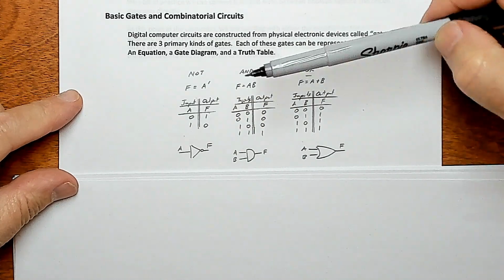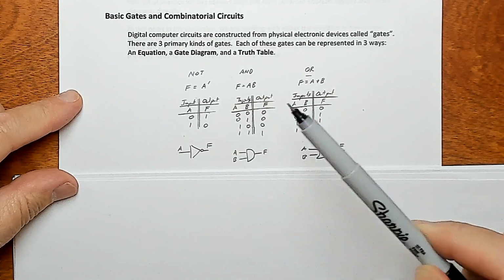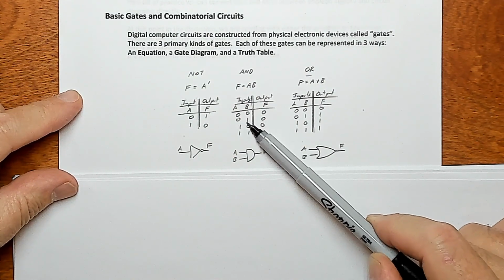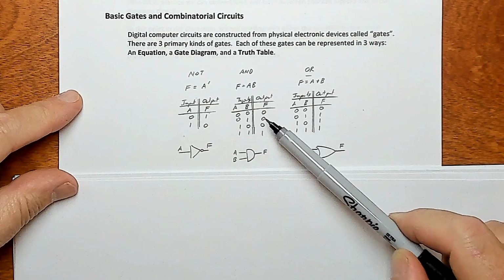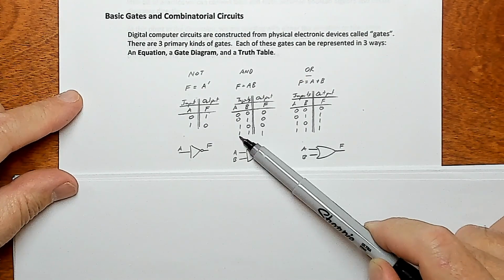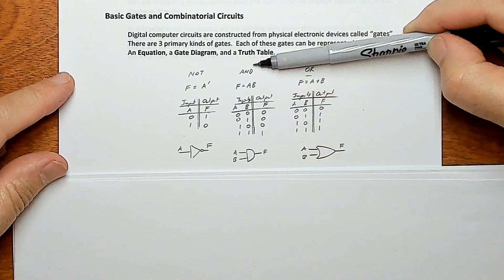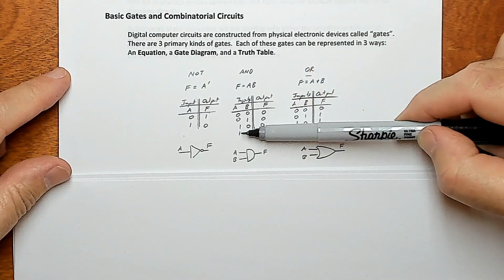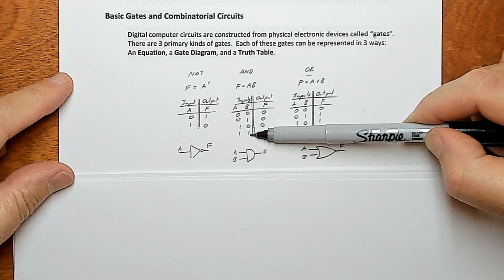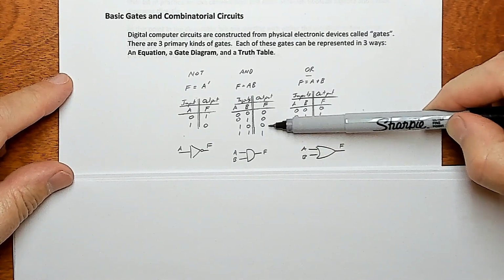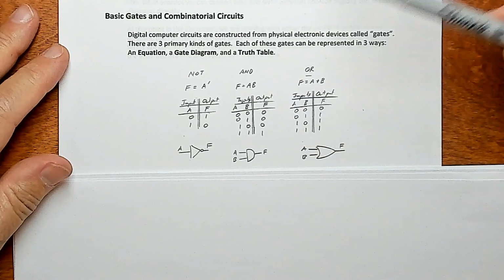Okay, AND is a binary operation. There are two operands, and if you put two zeros in, you get a 0 out. You put a 0 and a 1 in, you get a 0 out. A 1 and a 0 gets you a 0 out. A 1 and a 1 gives you a 1 out. So we've seen this before. AND is sometimes said as: the output of an AND gate will be 1 if both inputs are 1. Otherwise, the output will be 0. It's a way to say it in one sentence.